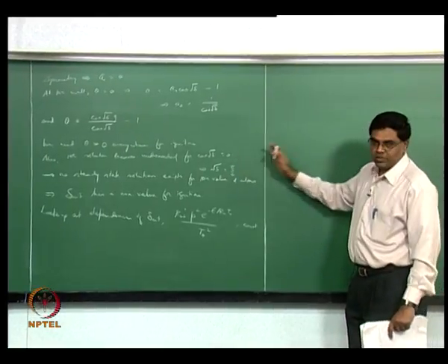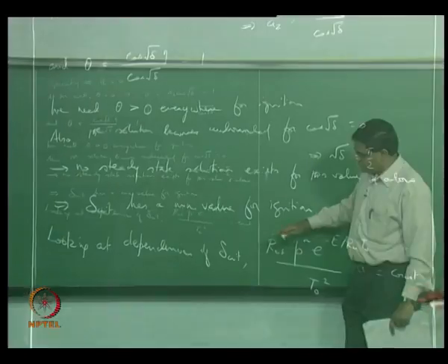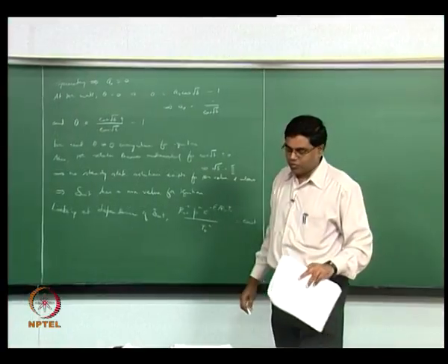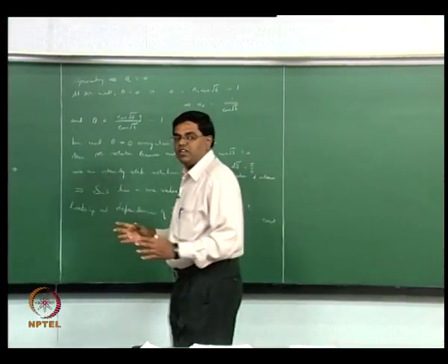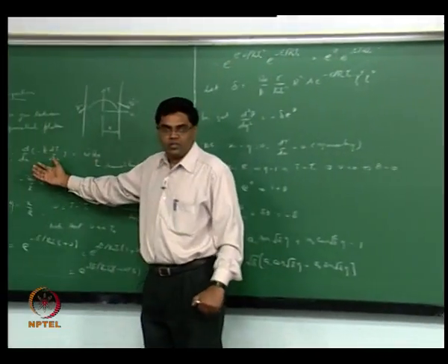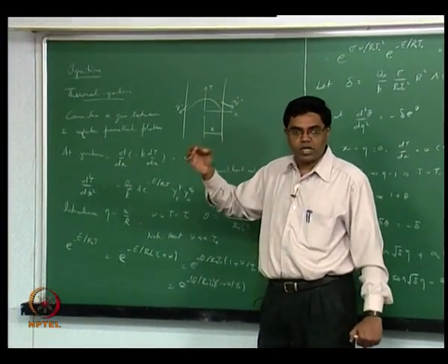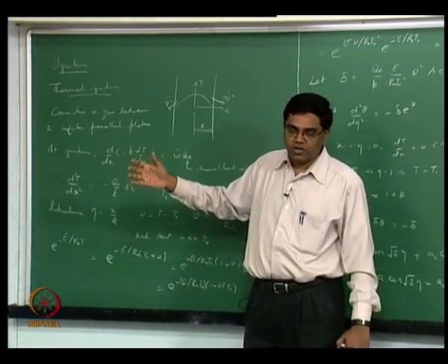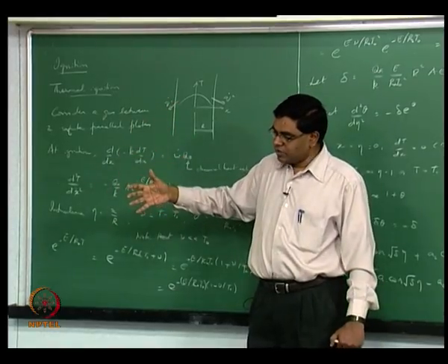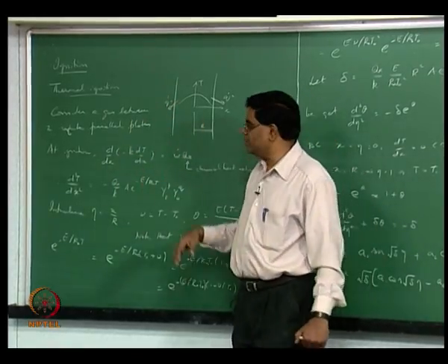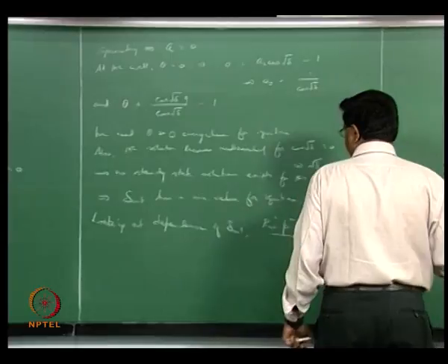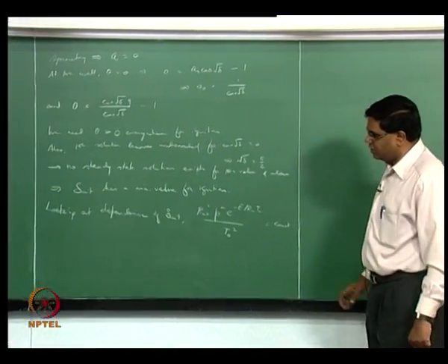and as I said, let's not even worry about the exact values and so on, but in reality this constant is empirical, it's not exactly this. That's because we are losing a lot of things. First of all, you're assuming a momentary steady state here, that this equals that at just this particular point, but it's a dynamic process. You have an unsteady process essentially, and we are not really worried about the variation in the temperature with time when this ignition is happening.